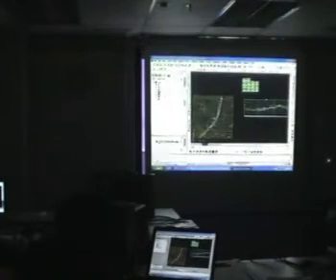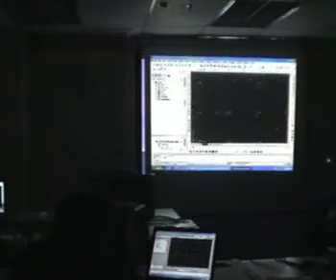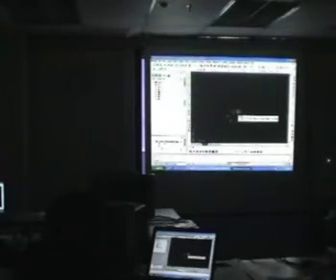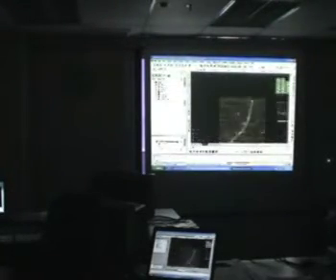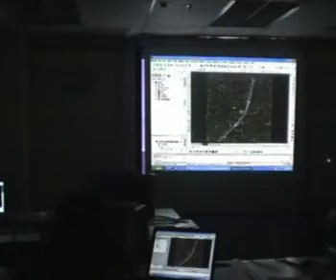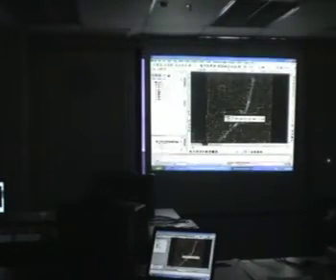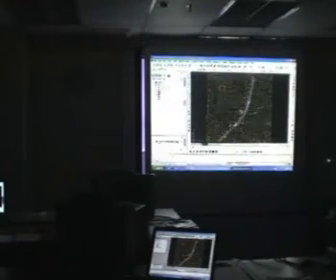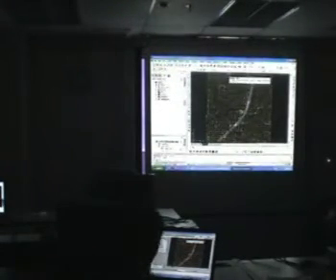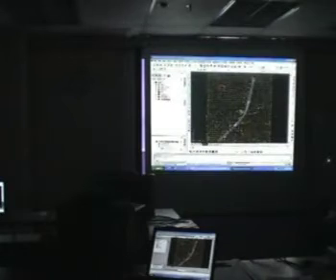I'm just going to zoom in so you can see these are actually all the points. The points are about the same as in Land Desktop, and I've already created the surface. Civil 3D is unlike Autodesk Land Desktop. In Land Desktop, to create contours, the elevation banding, the triangles, you have to go to Terrain and create them yourself. In Civil 3D, there's no Terrain option here. Everything is managed on the left-hand side.